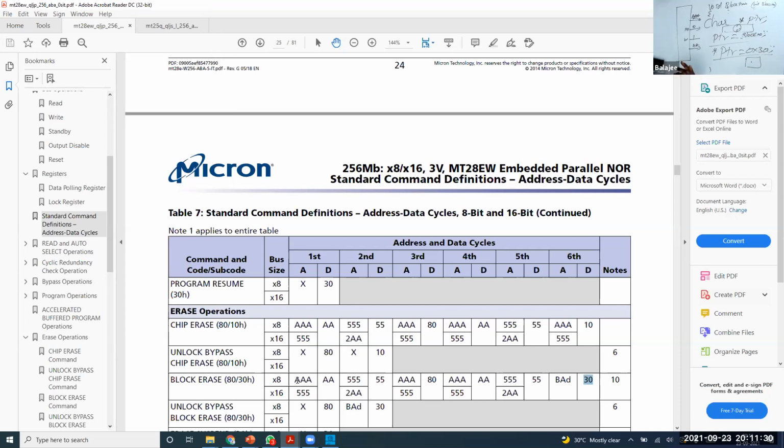If you want to erase 5 blocks, you can do 5 single-block erases. You cannot erase 5 blocks at once. Either you can erase the whole chip or 1 block. You can do only 1 operation. You cannot do all the things.